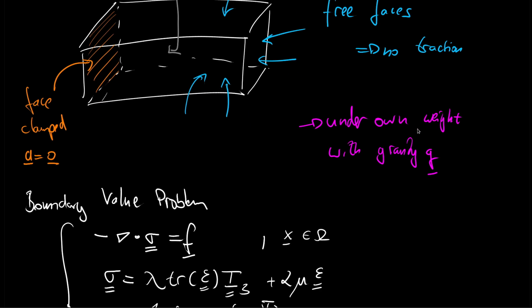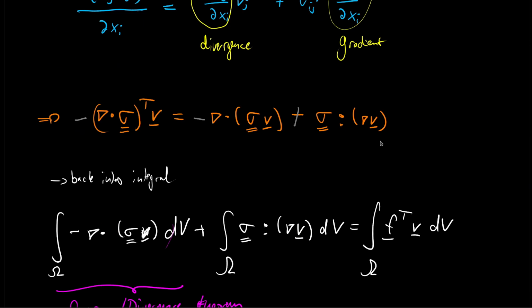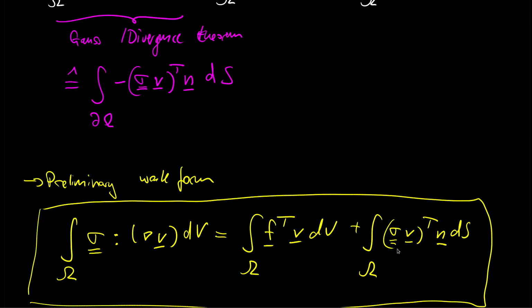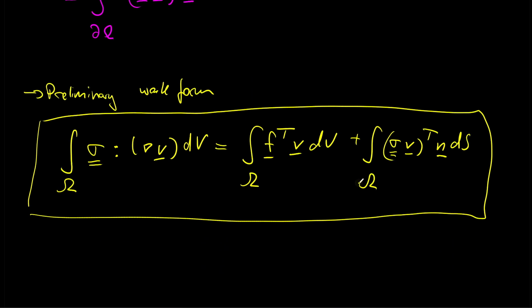What is t? So technically this is what you could already use within FEniCS, but we want to make that more concise or bring it into a form that is more commonly used in linear elasticity. But before we can go there, I noted a mistake, so this should be d omega to get the surface integral correctly. Well, then let's note down the two parts we want to change. So we have this one over here, I want to call 1, and then we have this other one, which we will look at afterwards.